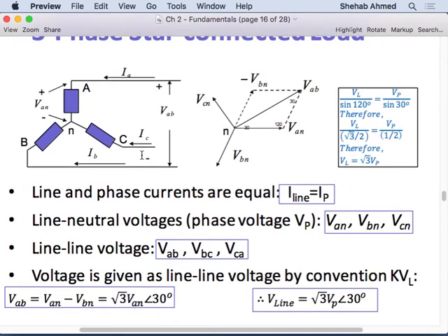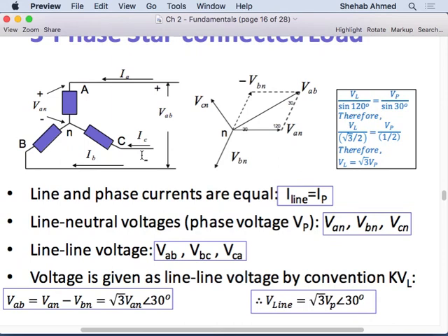Not because I don't like that, it's because our power systems have tens of thousands of nodes. So take these tens of thousands and multiply them by 3. And actually, when we solve power systems, we're also solving for many quantities, real power, reactive power. So we will typically have 2 equations at every node. We want to know the active power and reactive power at every node. There are 4 variables we will want to know all the time: active power at a node, reactive power at a node, voltage magnitude, and angle. For these 4 variables, we'll always have 2 given, and we want to always find 2.